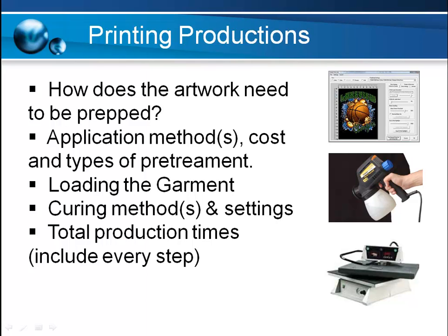The pre-treating process is one of the things that, in my opinion, isn't discussed enough prior to the sales process, and prospective customers really need to truly understand how important pre-treating is, because it's the foundation of your print. And if the pre-treatment process isn't done correctly, your print's either not going to look good or it's going to wash off. So understanding all the steps of how to apply, how to cure the pre-treatment, and then loading the garment onto the actual printer.